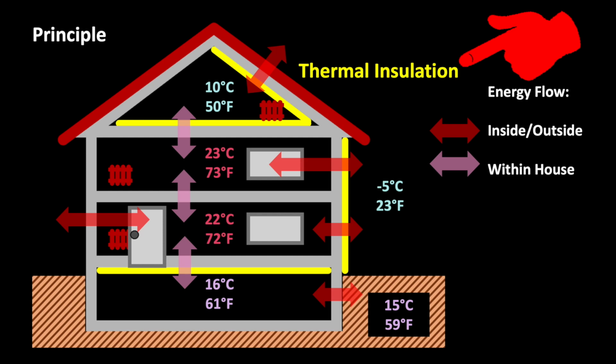That's the idea. If you want to calculate the thermal energy consumption using a real example, then a piece of paper and a pocket calculator are not enough to carry out these calculations. We will see why in a moment. On the one hand, many different heat flows at our interfaces have to be taken into account, outwards through the roof, through walls, through windows and through doors. In the basement, there is even a flow of heat energy to the ground.